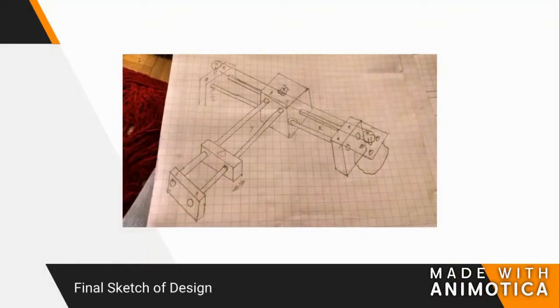This is the final sketch of the design. We went through a couple iterations before we decided on this one. The first iteration was based on a bearing and aluminum extrusion design, but after a couple runs, it was apparent that the aluminum created a groove on the plastic bearings we made, and we had to scrap the project due to not having tight tolerances. Thankfully, we had some linear actuators and bearing rods lying around to create our final design.